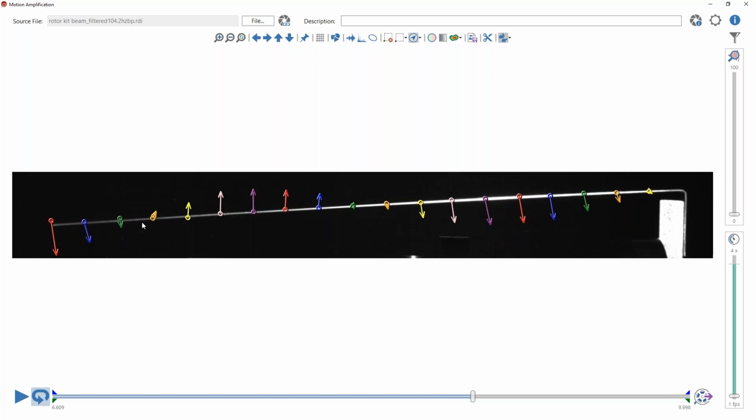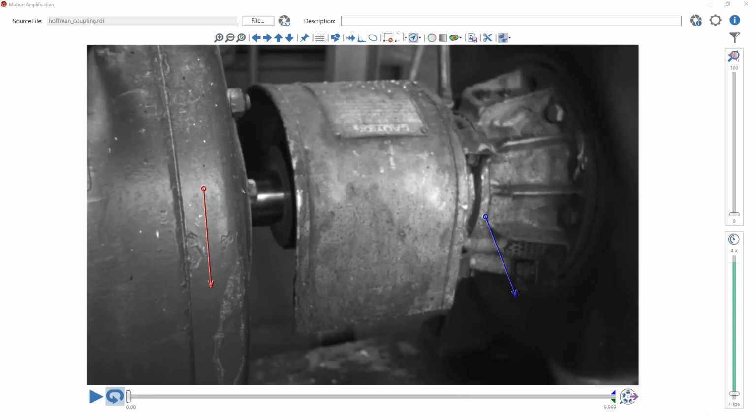So anyway, that's the concept of motion vectors on this one, and then finally, let me show this last mode of vibration. This is the fourth mode of vibration. Again, the vectors are really demonstrating this concept of directionality and level of motion, and also the shape of vibration, a complex way of being able to show that. Let me bring this into a real asset, right?